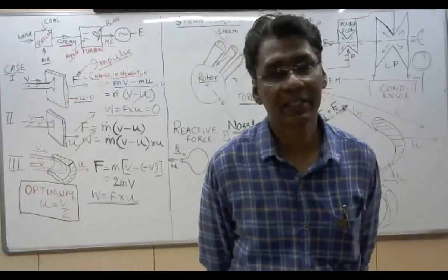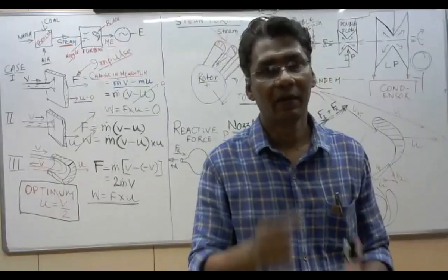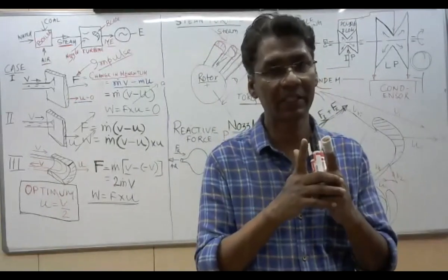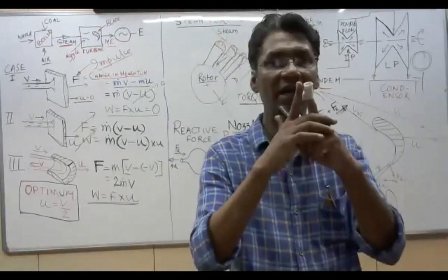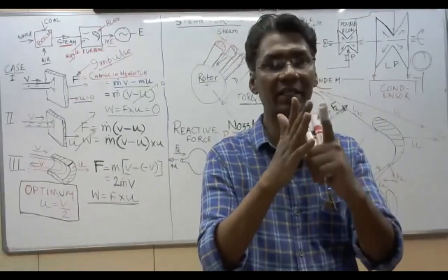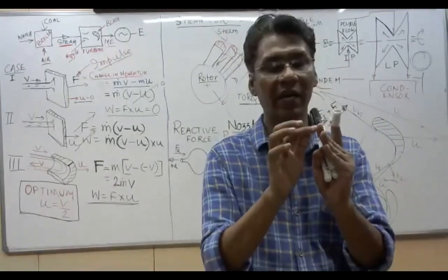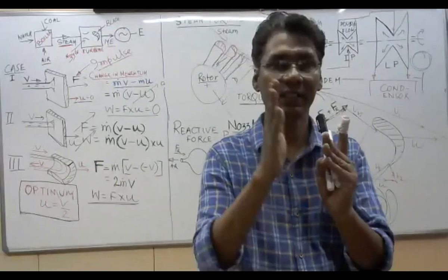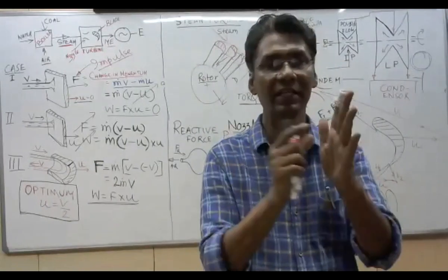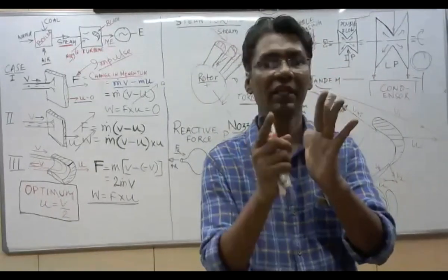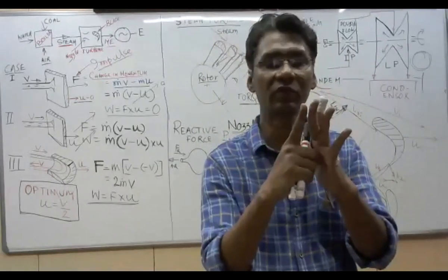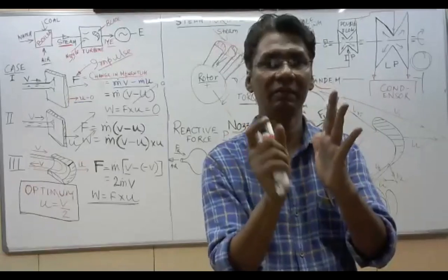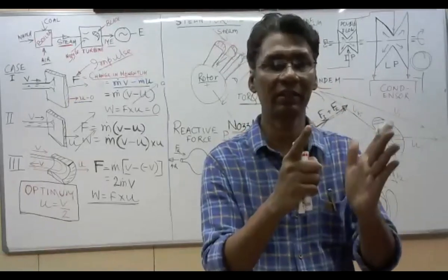There is a blade and a casing. The smaller the casing gap, the higher the efficiency. If we minimize the gap between the moving blade and the casing blade, the carryover loss will be minimum. But that is a restriction, because if there is axial movement of the shaft, it may foul with the stator blades. So it depends upon the allowable limit of axial shift, the clearance between moving blade and fixed blade.